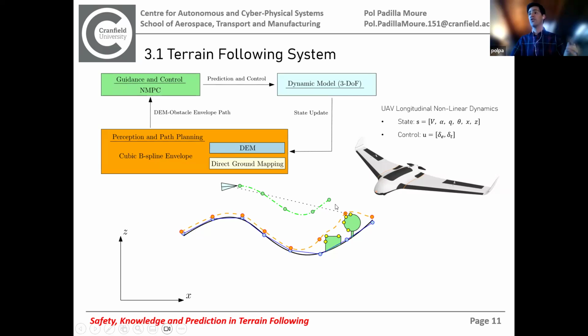After we have crafted this, in a much shorter prediction horizon we can use the NMPC so that the UAV can control and can plan a trajectory above the envelope that we have just gathered. So we've got these two stages and we are dividing the problem. We have a first stage that handles the two different sets of data, the two different time scales, because we are gathering data very fast, but we can afford to provide a longer prediction horizon. And then a second stage on a shorter time scale where we must handle the control of the aircraft. And we do not need the aircraft to plan, for example, 10 seconds ahead. For 2 seconds, it is enough to properly condition a stable flight on a fixed wing platform.